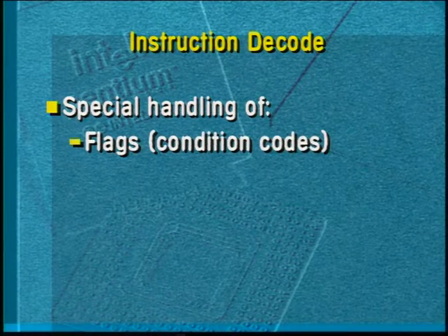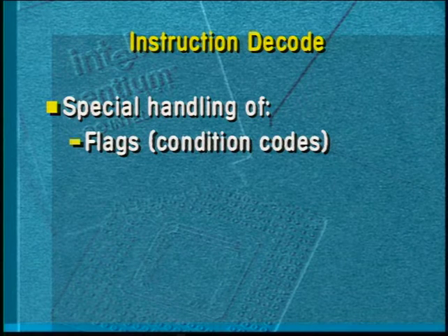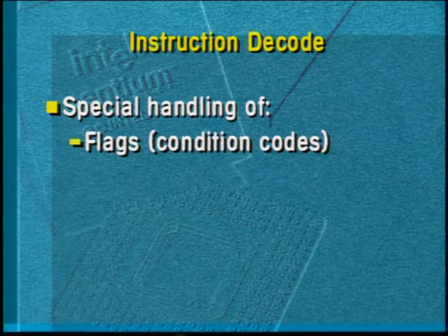First of all are flags. In the Intel architecture, most of the instructions modify the flags, so that without special handling, it would be difficult to pair many instructions. So we do handle the case of parallel instructions that modify the flags, and we update the flags the same as if the instructions were executed sequentially. We also have special logic that handles the case for conditional branch instructions executed in parallel with an instruction that sets the flags. This occurs quite commonly, especially for compare branch combinations.